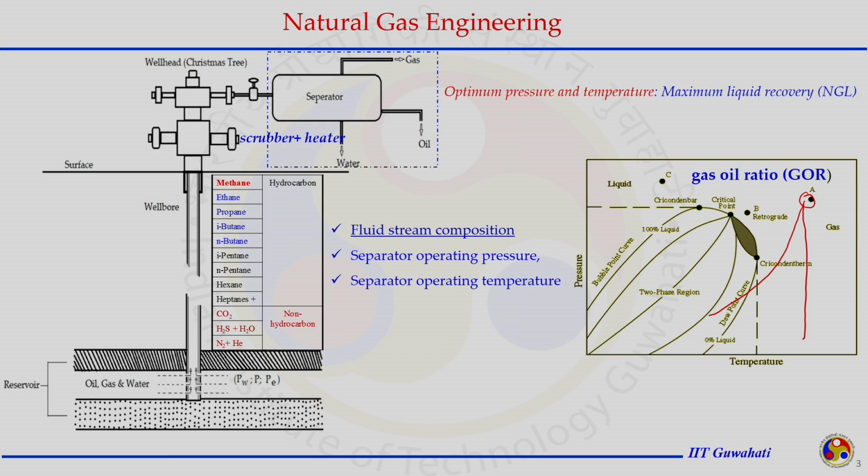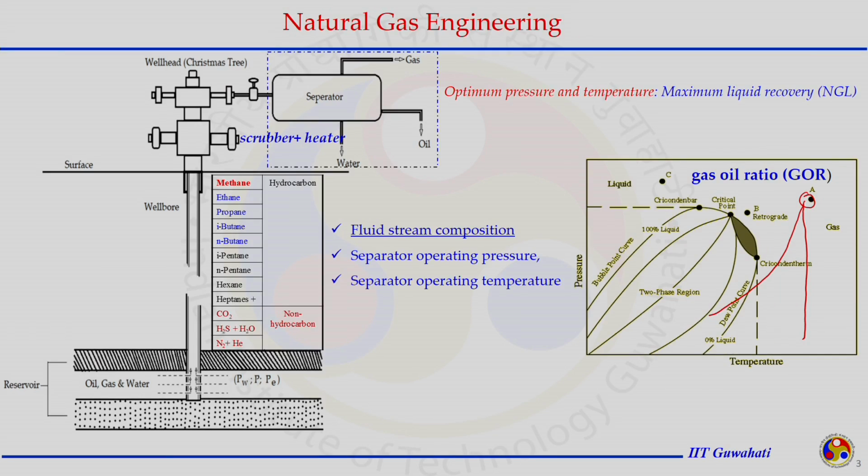So, when the gas reaches the separator, again pressure drop will happen, and under that condition the separation of gas and liquid, those actually present in gas and liquid condition, will occur, as well as some of the compounds of the gas may go to liquid, or some of the compounds of the liquid, because of revaporization, are going to the gas phase at the separator.